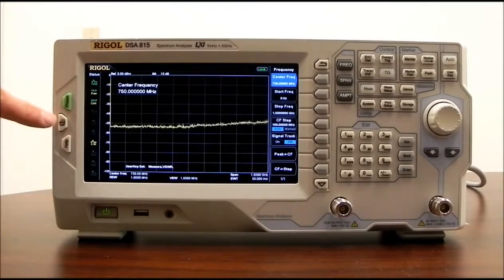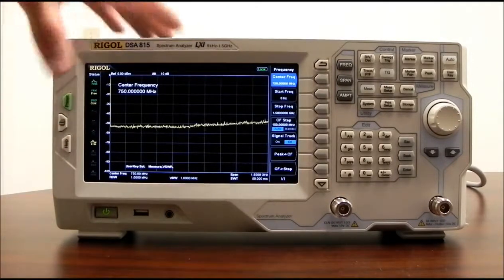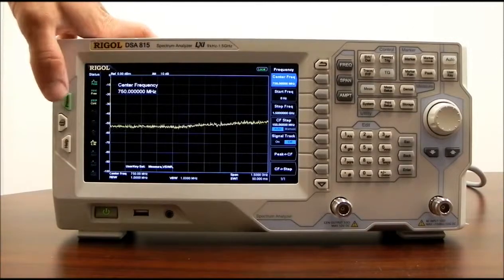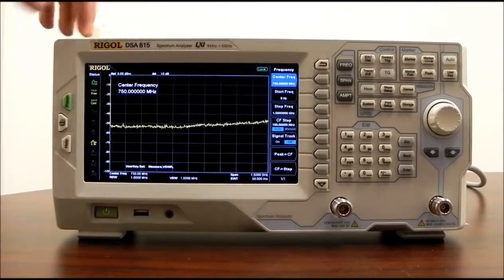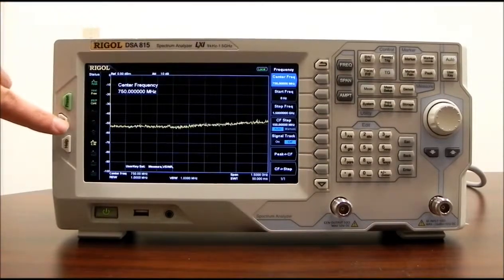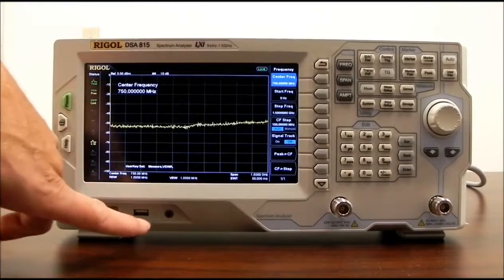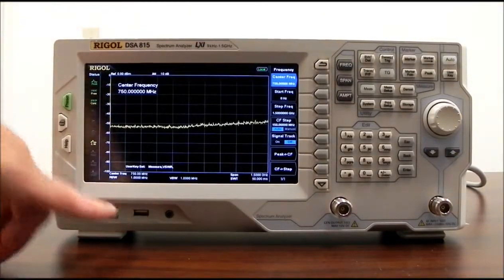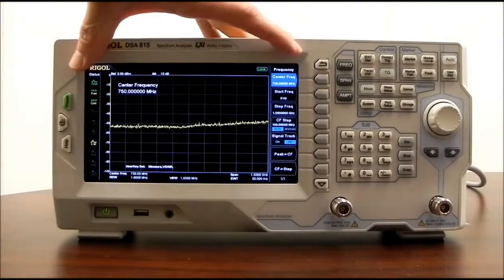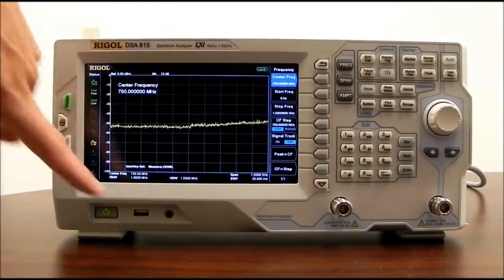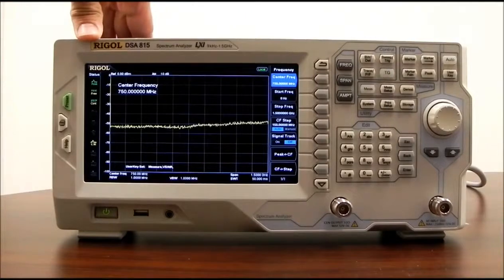We have a help key, we have a print key, and a preset. Preset gets us back to whatever conditions we program that preset key for. That can be very helpful. In this case, I have it set to factory defaults, so by pressing it, I go back to factory defaults. The print key, if we put a USB memory stick into the front panel, we can configure the print key to print a bitmap image of the full display as well as the menus and settings directly to that USB drive, which can be extremely helpful.